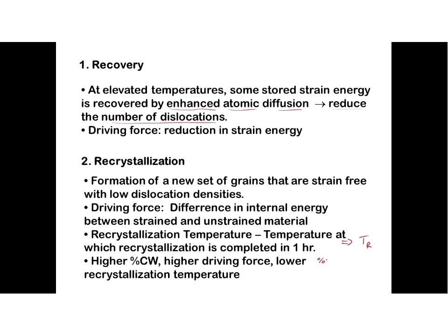So as the percent cold work goes up, the recrystallization temperature goes down. It takes less heat to get things to recrystallize because there's a greater desire for the energy to equalize. There's a large imbalance in strain energy.